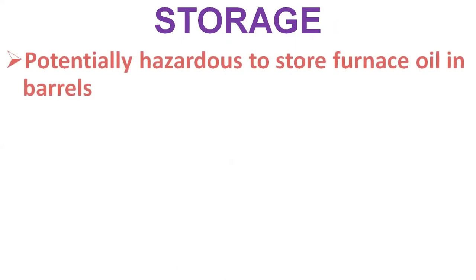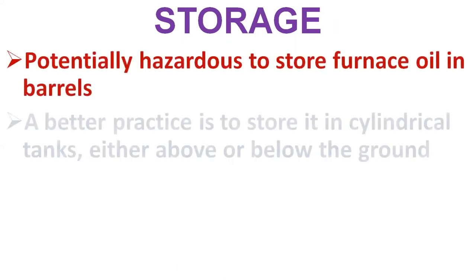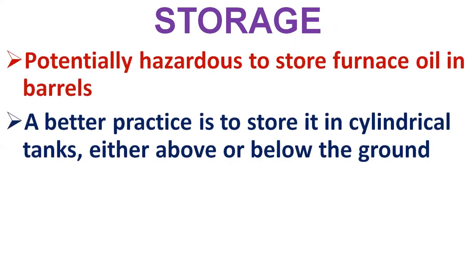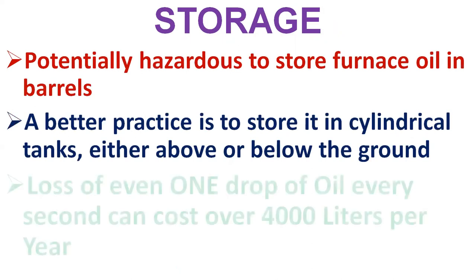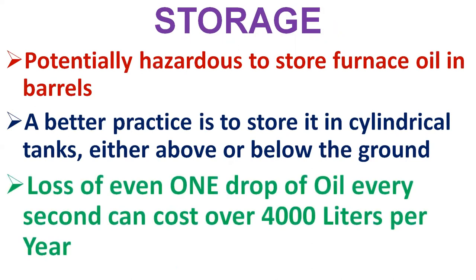Then the water content of a furnace oil when supplied is normally very low, as the product at the refinery site is handled hot, and a maximum limit of 1% is specified in the standard. Water may be present in free or emulsified form and can damage the inside furnace surfaces during combustion, especially if it contains dissolved solids.